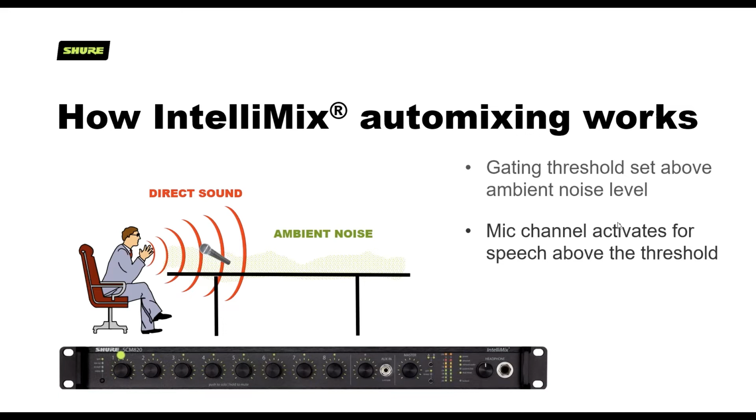However, noise and musical program material can be much more similar in terms of their dynamic characteristics. And what that means is that musical information can confuse an automatic mixer. They really are designed for speech only, which is very dynamic, right? Speech is loud and soft, loud and off, and that's how the mixer is able to determine that it's speech. But we commonly get calls from people who run their choir mics through an automatic mixer, where the choirs can be very ambient, in that you might hold a note for a long time, hold a chord for a long time.